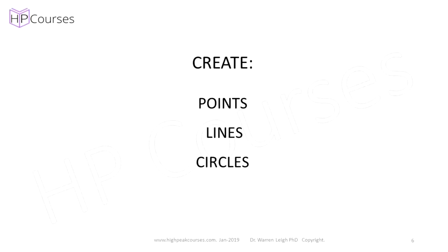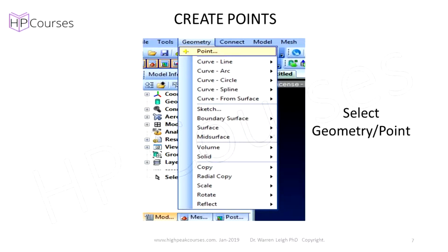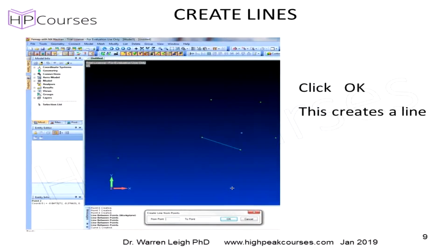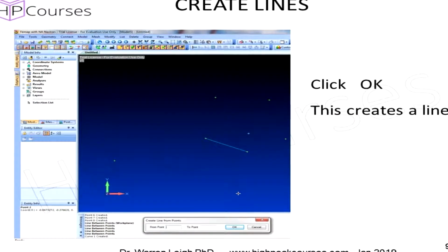So in Femap, we start by creating 4 corner points of a panel of the stowage unit by entering the 3 X, Y and Z coordinates of each corner. You can create line 1 between point 1 and point 2, by selecting with the cursor point 1 and then select with the cursor point 2. A line will be created in Femap.